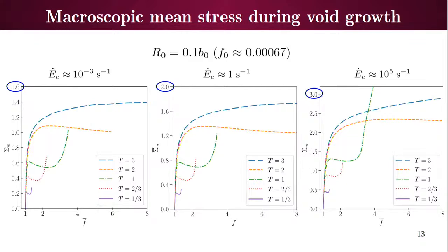So we are basically looking at how the mean stress is varying with respect to void growth. This is normalized void volume fraction with the initial size. We see a similar kind of response at all the strain rates. With varying triaxiality, the void growth increases with increase in triaxiality. The void volume increases more and more as the triaxiality is higher.